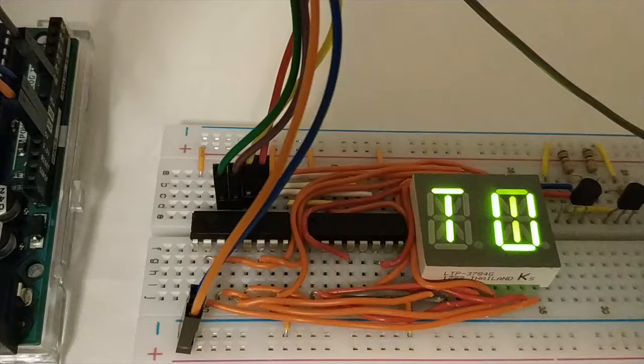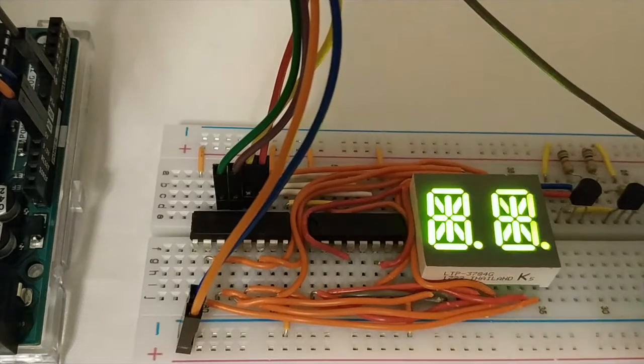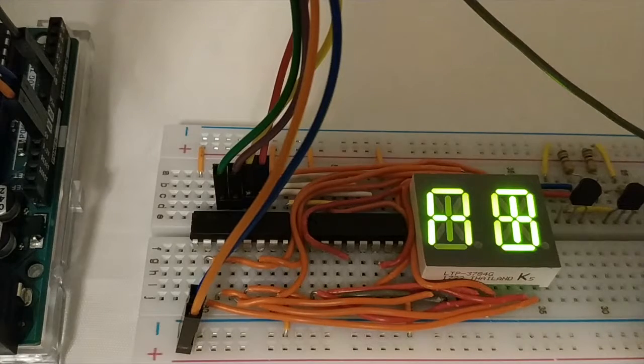In this project, PoV is used to create that effect. The base pins of the transistors are either given a high or low signal, pulling the common cathode pins of the digits to ground or not, illuminating one digit of the display at a time.